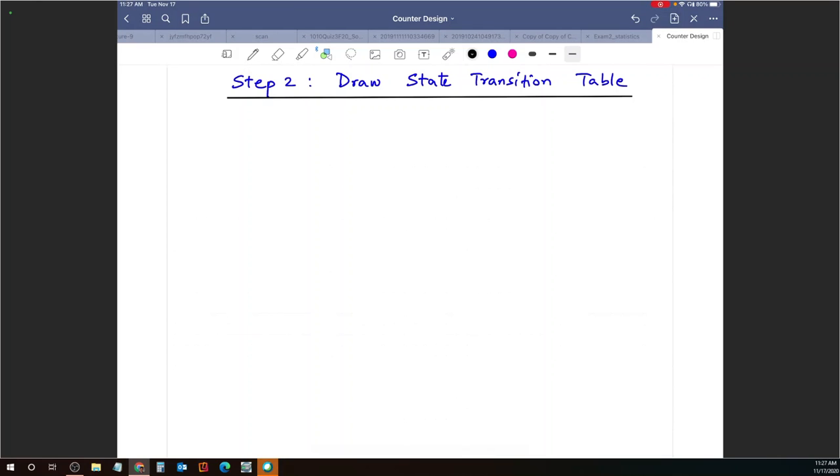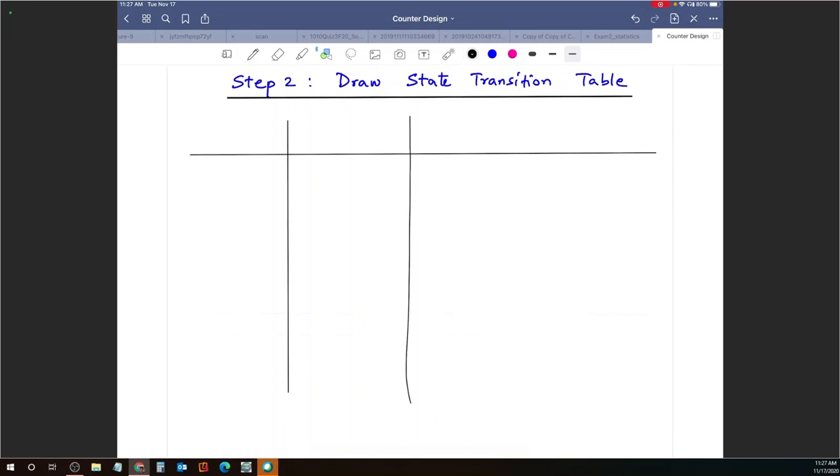All right, so for this, I'm going to start with my current state. Let me draw a big table here, right down the middle. Now for the headings of the table, I would need QC, QB, QA. Why do I need 3 of them? Because it's a 3-bit counter, right? Those will transition to QC plus, QB plus, and QA plus after the active edge of the clock.